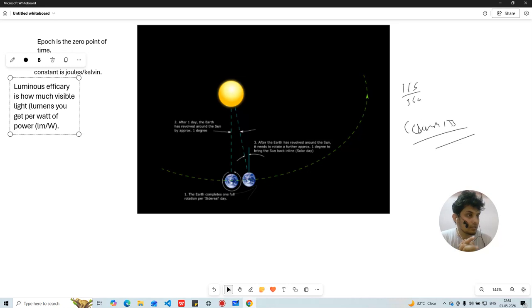So crystal oscillators, all these are ways to generate a stable clock signal using a quartz crystal. The crystal vibrates at a precise frequency like a tiny tuning fork. The difference between them is how well the controller adjusts that frequency. Quartz exhibits the piezoelectric effect. Apply voltage, it vibrates. That vibration gives a very stable frequency. VCO is a voltage control oscillator.